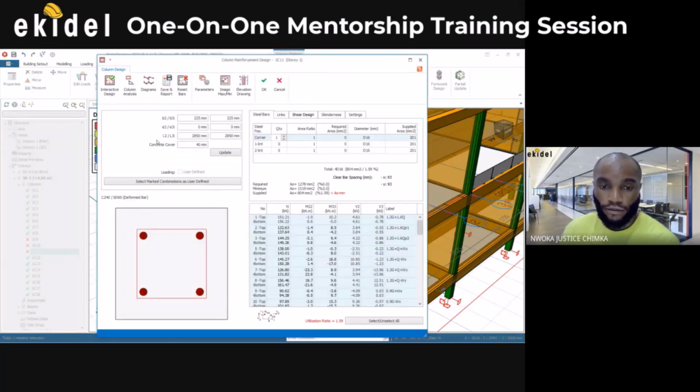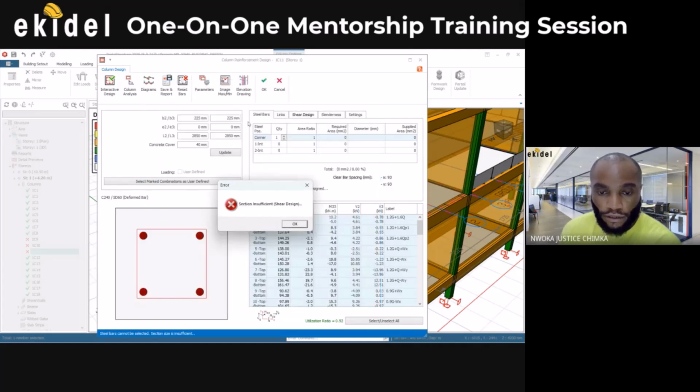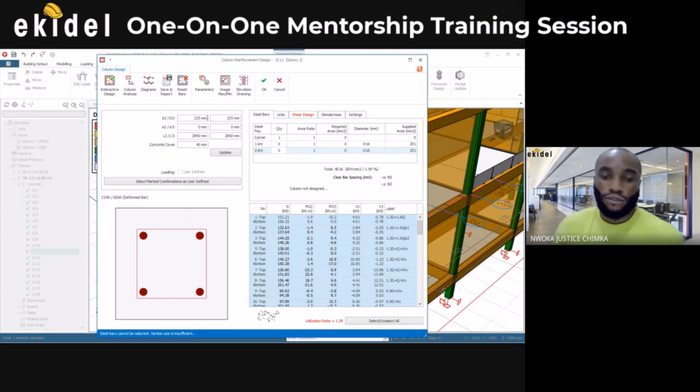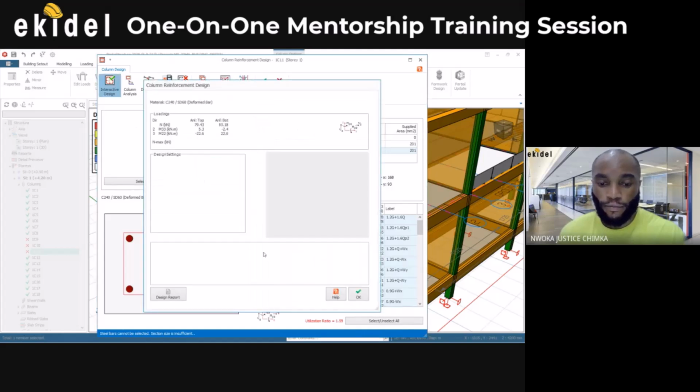Then design now. It's still the same thing. It's giving me the same thing. Okay. All right. You have to increase the size then. Yeah, it's the same thing. Let me see. The 300. No. Yeah, it's still the same thing. So just increase the size. Let me say 300. And we can still have a rectangular column instead of square. Okay. So just say update and then design again.